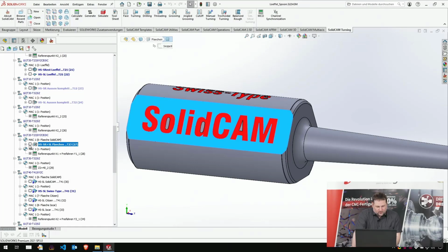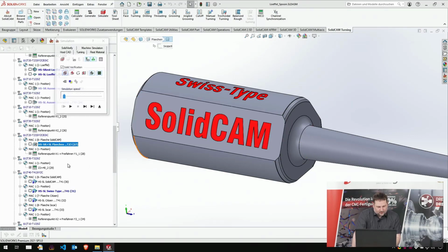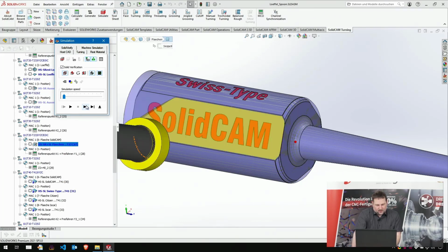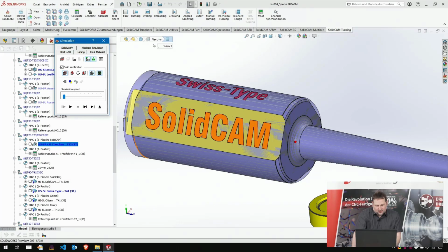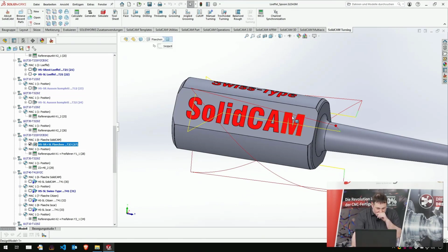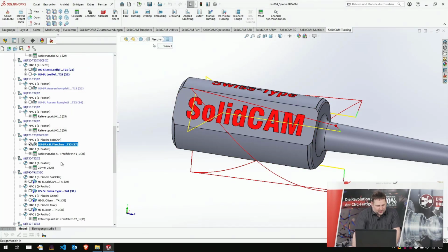For the faces here, we are using a profile operation, just a straight line to get the best, the shortest machining time. We have just one single line, down, up, one finishing cut, and then the next. And then we transformed it around because there's no need to make 3 jobs for each phase. We can just make one operation here, and then we say, okay, transform this operation around the 4th axis 2 additional times.